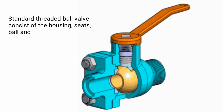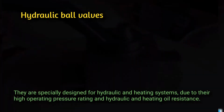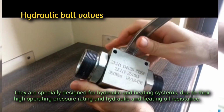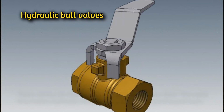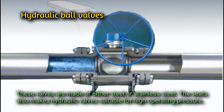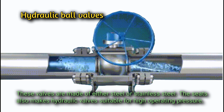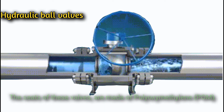Hydraulic ball valves. They are specially designed for hydraulic and heating systems, due to the high operating pressure rating, and hydraulic and heating oil resistance. These valves are made of either steel or stainless steel. The seat also makes hydraulic valves suitable for high operating pressure. The seats of these valves are made of polyoxymethylene, POM.